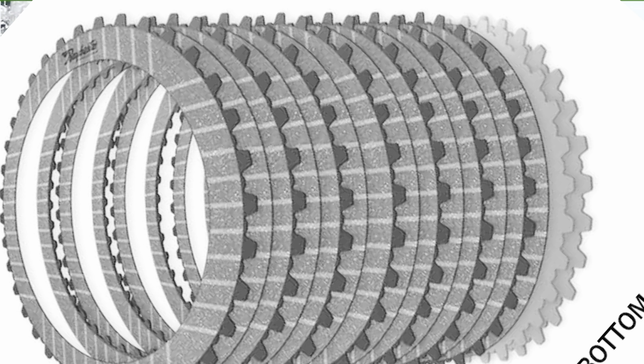If both the clutch pack and the band were released, the system would be in neutral. Turning the input shaft would turn the planet gears against the sun gear, but since nothing is holding the sun gear, it will just spin free and have no effect on the output shaft. To place the unit in first gear, the band is applied to hold the sun gear from moving. To shift from first to high gear, the band is released and the clutch is applied, causing the output shaft to turn at the same speed as the input shaft.